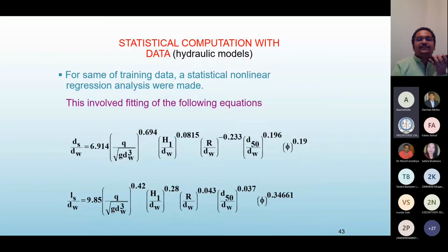Okay, see here, as you told, there's no statistical. You can see how much importance, 0.94, this one Froude number. This one relative head. Bucket radius, you can see inversely. That's why this one, lip angle, is also always very important. In case of location of scour, you can see always here 0.34. That's what I observed, and also always the Froude number is important. That's why I will also show you perturbation analysis, in case data is erroneous.